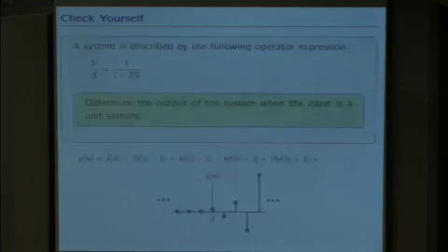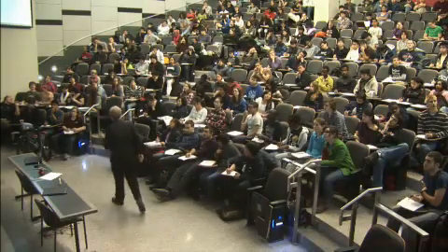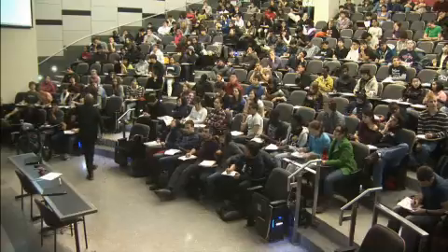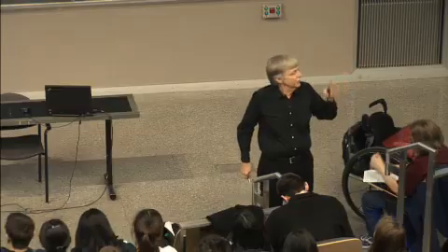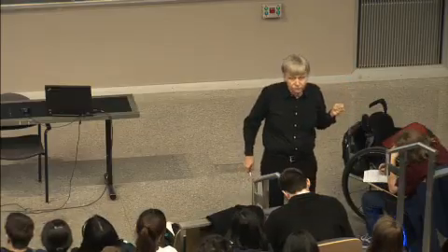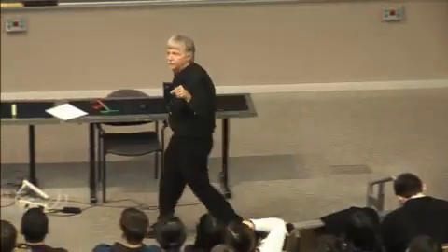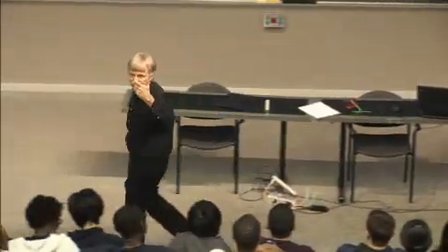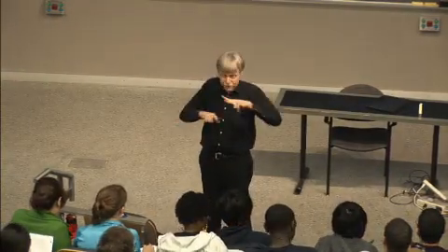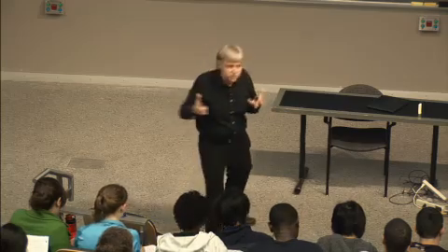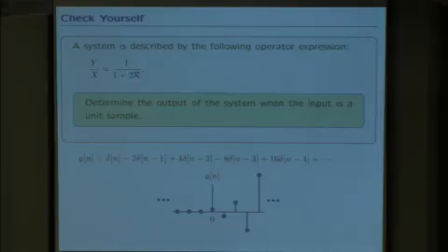And that whole mess then just says that my output looks like this. If the input was x, which was a unit sample signal, my output has an infinite number of terms. Each one is a delayed version of the predecessor. And the weights go 1, minus 2, plus 4, minus 8, plus 16, and diverge. OK? So what we just did was pretty complicated. We just solved a block diagram, but we did it with polynomial math. We did it with math that you learned in high school.